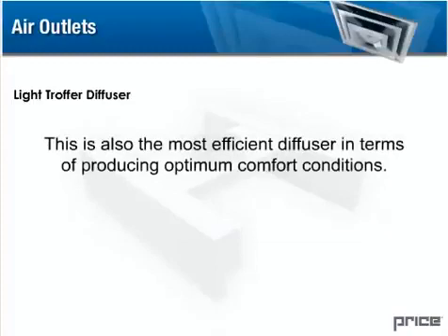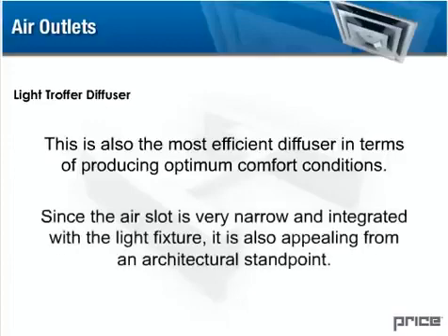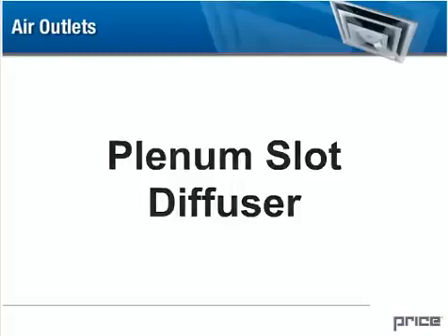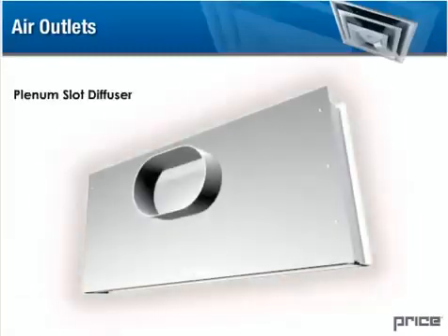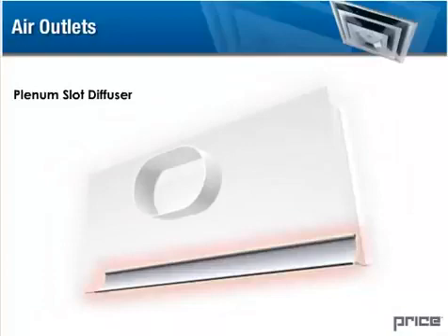This is also the most efficient diffuser in terms of producing optimum comfort conditions. Since the air slot is very narrow and integrated with the light fixture, it's also appealing from an architectural standpoint. Plenum slot diffuser. These diffusers consist of a factory-fabricated plenum with integral pattern controllers for vertical or horizontal air pattern